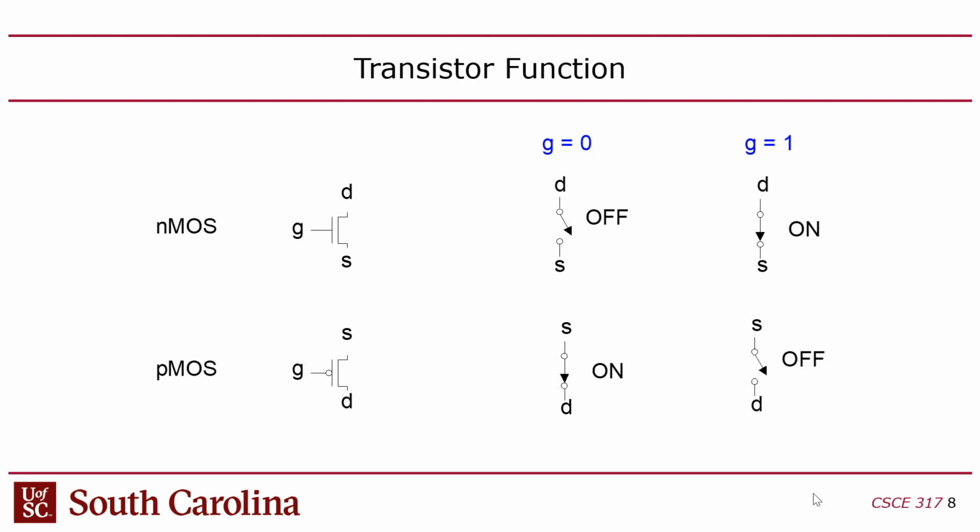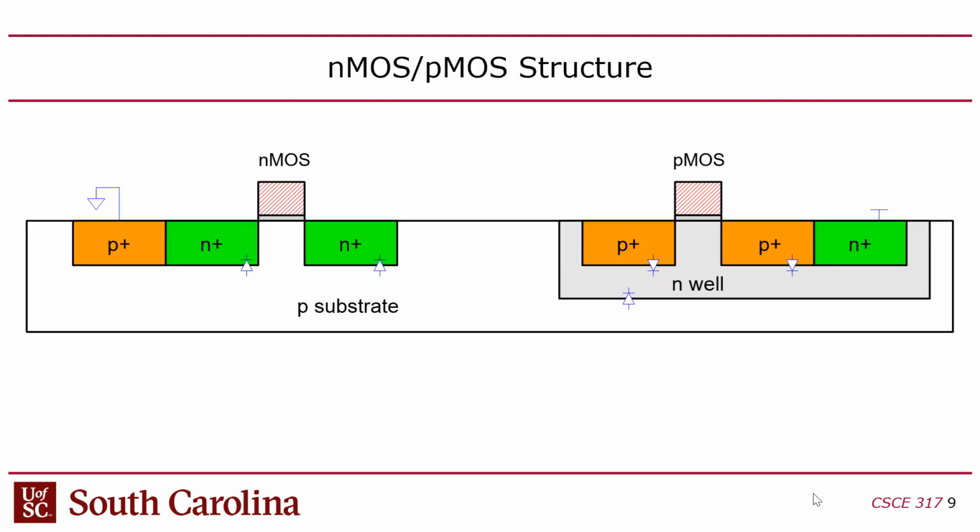In this case, PMOS is going to charge up capacitors. So I'm going to take current from the power supply through my source terminal, and send it out the drain to the gates I'm driving to charge up their gate capacitance to turn them on. So that's the function. That's really literally what's happening here.